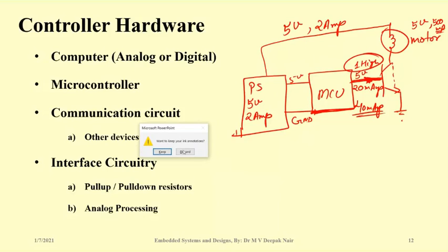So the power supply that we see here will generate spikes at the microcontroller side also. The microcontroller might possibly switch on and off, on and off, again and again. Understood? Because of the motor, the power supply may get spikes, and those spikes can even distort the input at the microcontroller. The microcontroller will run only if it is having 5 volt. The moment there is a negative spike somewhere around 2 volt or so, if it goes below that, the microcontroller will stop.